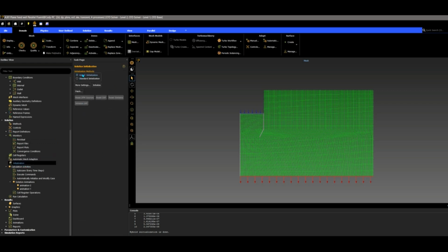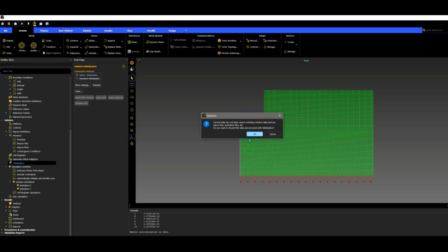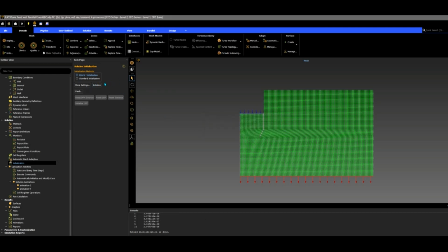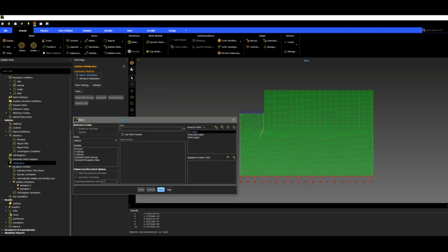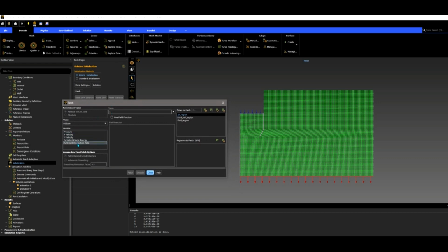So we've done a hybrid initialization, and after we initialize the simulation, we can go ahead and patch it. So patching just here, we're going to select aerated SPL, volume fraction, set that to 1, and make sure that the volume fraction is 1 for the SPL aerated in the feedwell region, so that's making sure that initially this